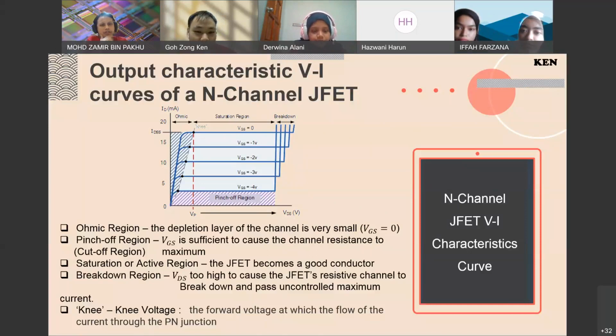All right. It's interesting to look into this, because what we see on the curve is the effect of the current control mechanism. JFET is a voltage control device. You use voltage to control the channel conduction. Going back to the physics, as I said last time, it's always related to the physics of the device. At some point on the curve, the device can no longer modulate the current because it is now broken. So it has to go back to the depletion width, because that's how you control the channel conduction or the current flow.